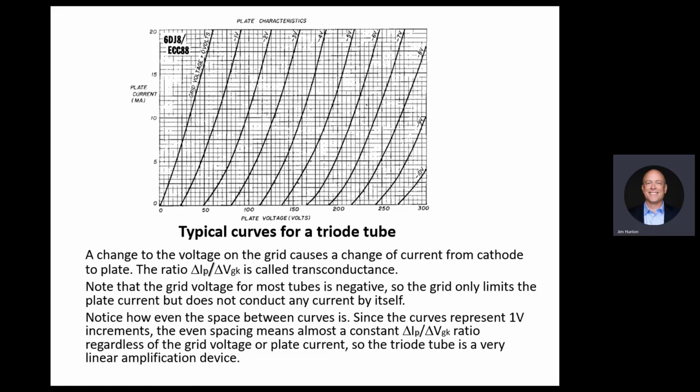You say, I want to put so much voltage, so much current. Now, in some cases, you have limitations. The tube cannot take more than so many volts, you cannot exceed. Or the tube cannot take more than so many watts. So the voltage you put on the tube times current, if you move to a higher current point on the chart, puts out more power dissipation and more heat. And then your tube life goes down. So it's a chain effect. This is part of the decision of the designer, how to pick the best operating point that is still reliable.